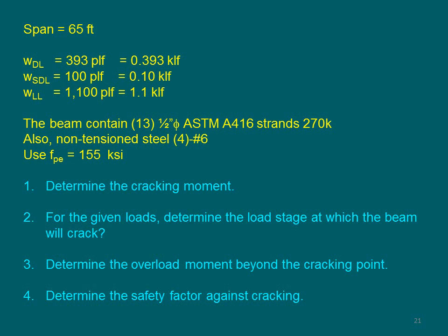It means I'm going to stay here a long way for the live load above the cracking. Let's say another scenario. I added dead load, I added superimposed dead load, I added maybe 1000 PLF of the live load, and no cracking is happening. Once you start here to add one more PLF above the 1493 PLF, I start to see some cracking.